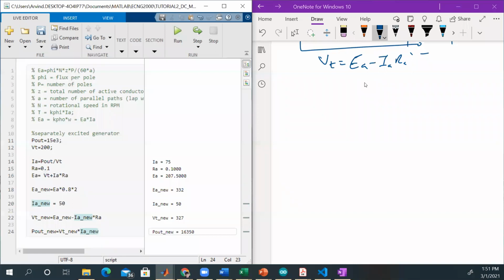So you could probably overload the motors a little bit more, pick up some extra load. Well, actually that analogy works more for the generators and the power system. You have to bring on additional transformers. You have the load growing. When do you put in a new transformer? Well, you can overload this one for a particular time before you change it. It will shorten the life.